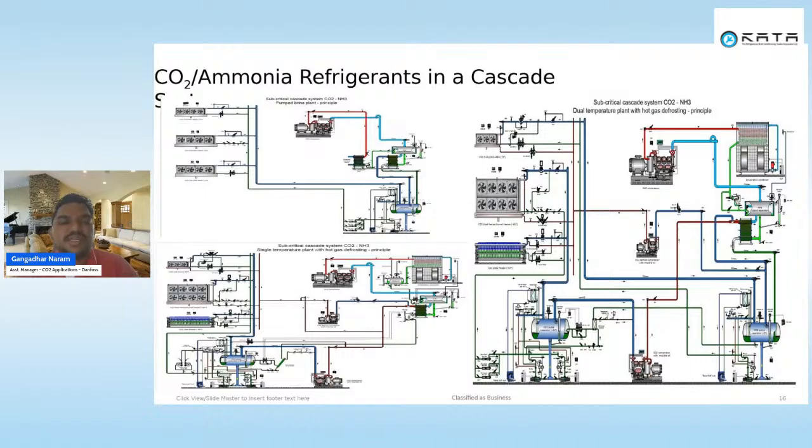All these industries in general operate from minus 25 to minus 30 degrees centigrade, all the way going down below to minus 45 degrees centigrade. Nowadays, we are using ammonia as the primary refrigerant for all these industries because ammonia is cheap, it has one of the best thermodynamic properties, and it is best for industry.